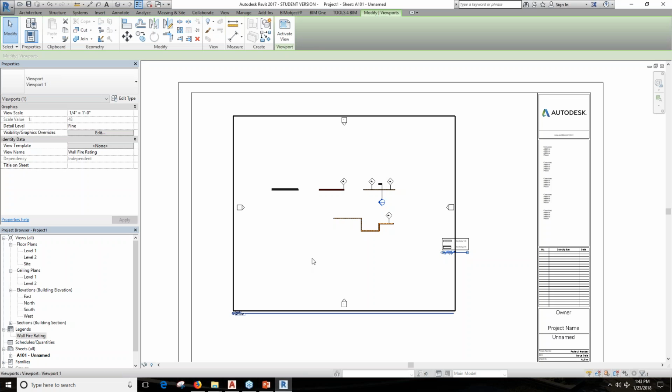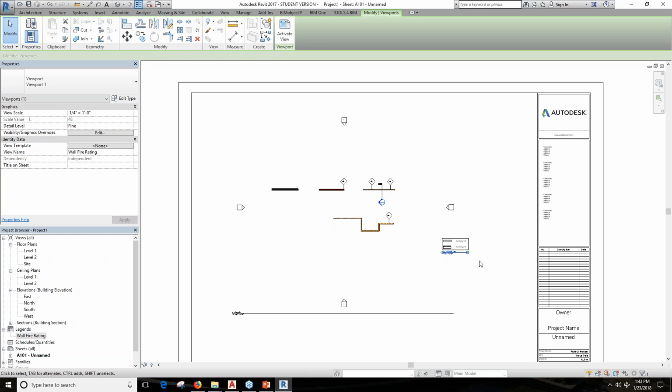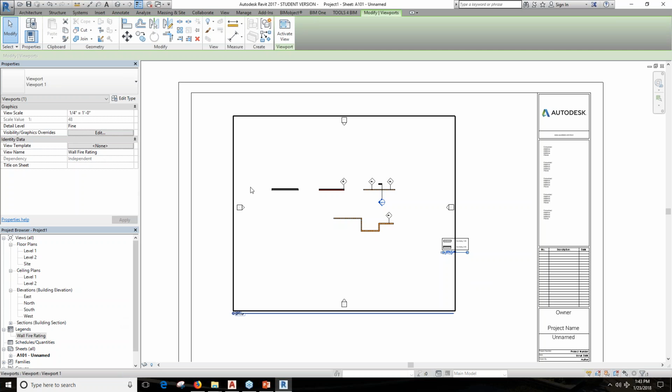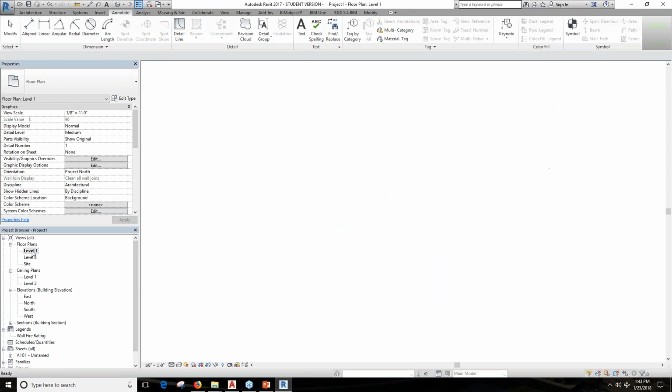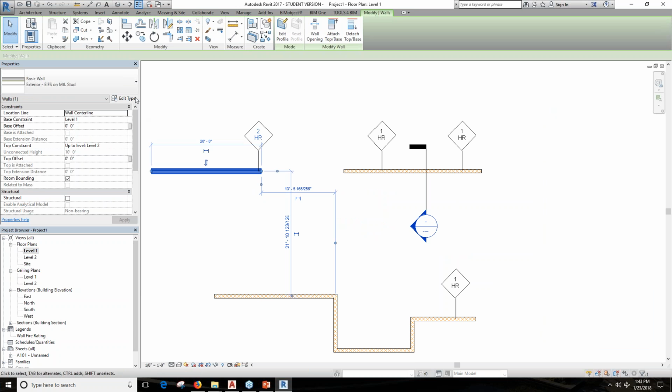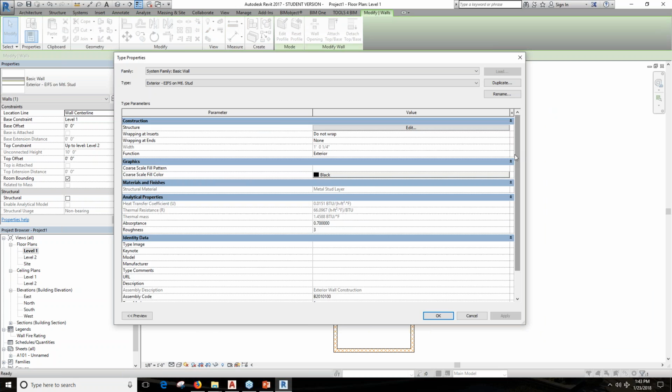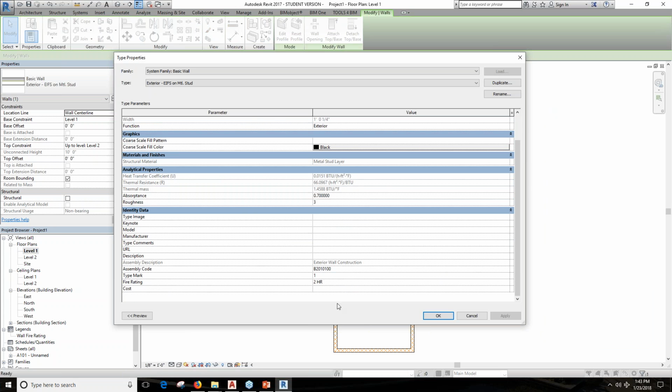when you actually are in Revit putting on paper or creating legends or actually taking material takeoff, those walls, if I go back again to the levels and you select those walls, the fire rating parameter is there, so you can bring these into the material quantity or schedules, and they will be shown which wall is with fire rating and which one is not actually using fire rating.